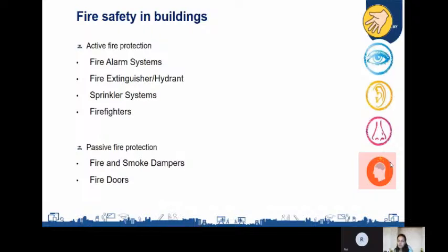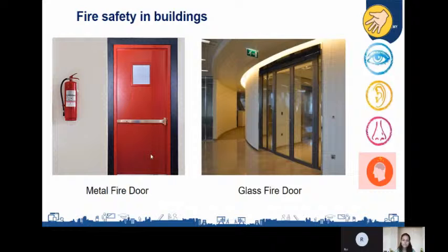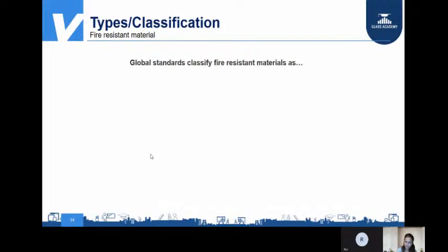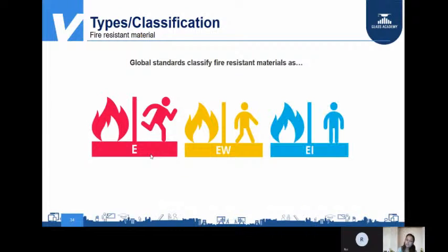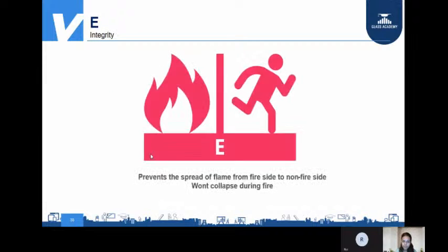So the normal application, if I have to say, is the windshield of your car. That is my laminated glass. If you might have seen, if that particular glass breaks, the glass pieces will not come on you. It will stick to the PVB layer. So if you ask me which one is the safest glass, tempered, HS or laminated, I will tell you that laminated glass is the safest glass.